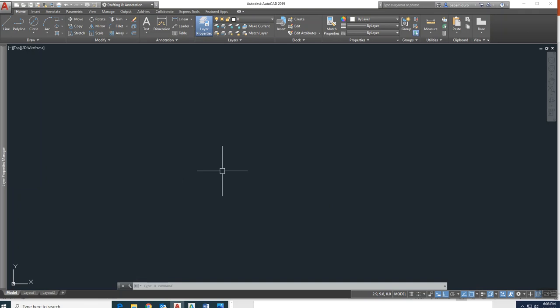important aspect of setting up your drawing space is you want to be able to create your limits. And I want you to Google this or look in your textbook what limits are. So limits typically just tells you and I that this is how much drawing space that I want. Now it varies if you're using metric or if you're going to use imperial, okay? So in this case, I'm using an imperial system, right? And I'll go back and show you what I mean by that.